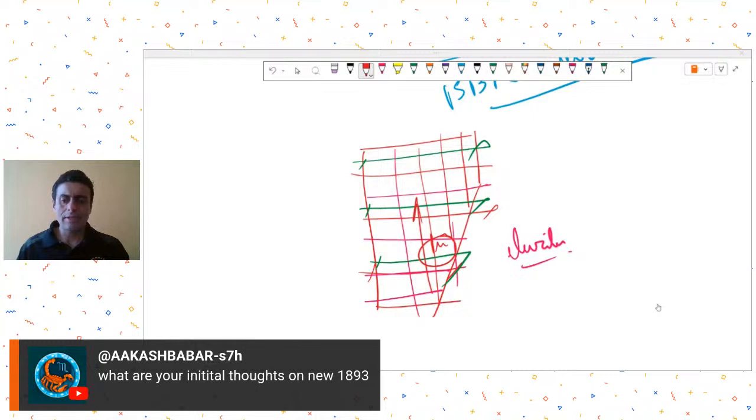But what I have heard is that they are trying to make it in line with ASCE 7 and the other international earthquake loading codes. So the probability levels have been revised. They have now started giving you the mean recurrence interval, and the earthquake forces are given as per the mean recurrence interval periods.